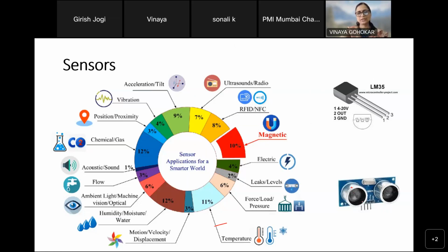This sensor helps in many applications, initially designed for finding obstacles. It has a transmitter and a receiver. The transmitter sends the signal, and if something comes in the range of the signal, the reflection coming from it is measured by the receiver. Depending on the time of flight, the time the signal takes to go to the object and come back, you can measure the distance. You can use the same thing for measurement of velocity further, because these things are related to each other. So it is a simple sensor which will help you find out the distance of the object.